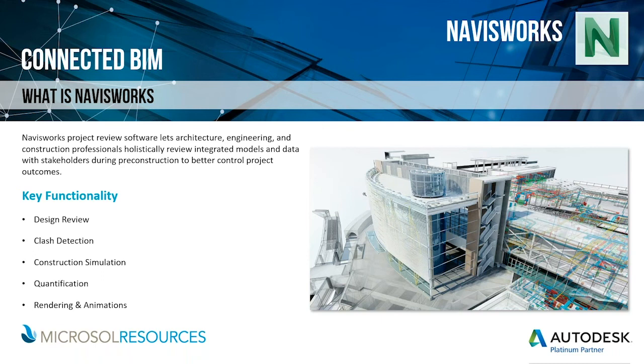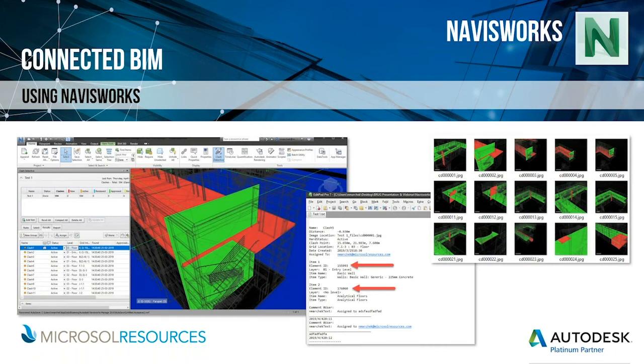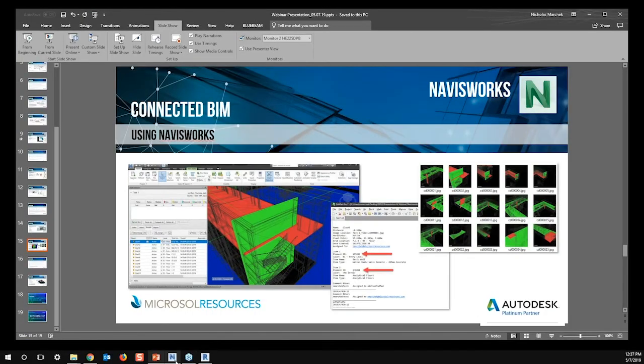Construction simulation through the Timeliner tool, takeoff quantities from the model or models and exporting to Excel or other costing software to use in that manner. Also, it can even be used for rendering and animations. So here's just a couple screen captures of the clash detection, and I will show that to you here in a second. So let me just open up Navisworks.